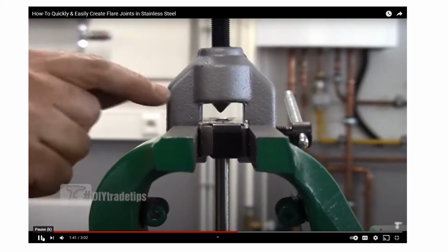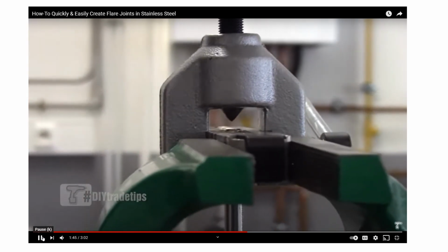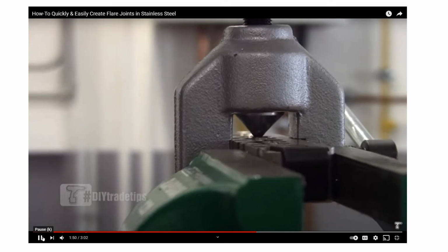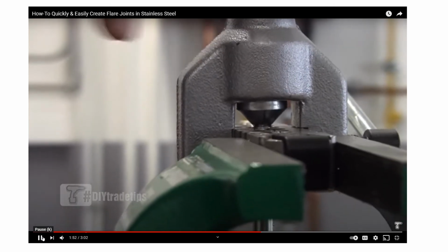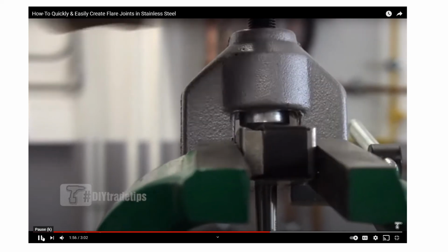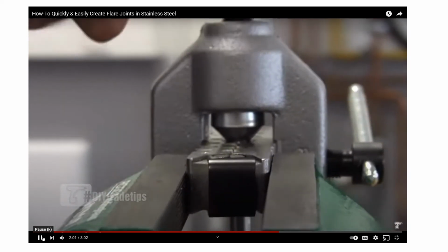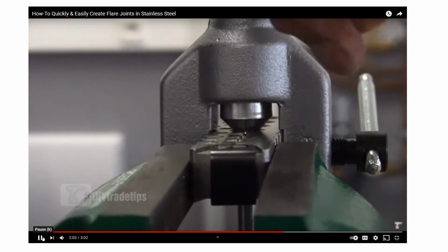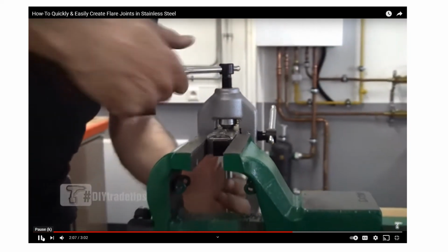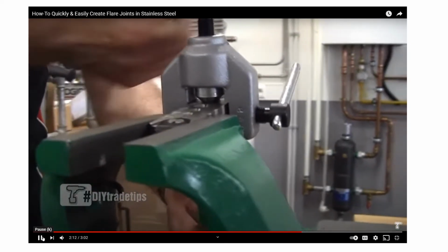Okay, so we've got the tube set in the flaring bar. We've used a vise just to help us here. And as you can see, as I turn the handle, down comes the cone. Just to make things easier, if it's not an issue, you can lubricate the cone. And all you simply do now is just turn that handle, and the cone is on an eccentric. So it actually sort of spins round and forms that tube end into the flaring bar to give you the flare. When you've bottomed out, you can't go any further.